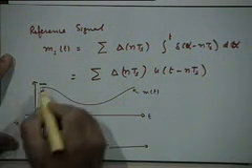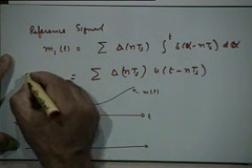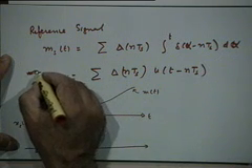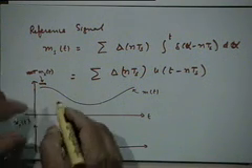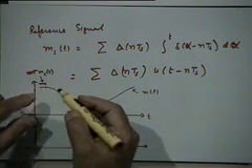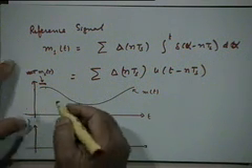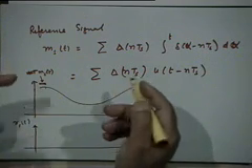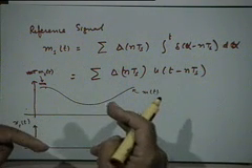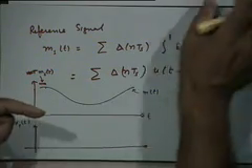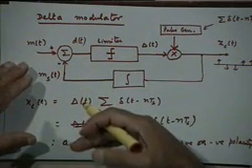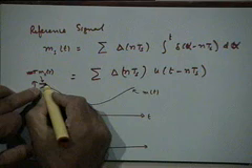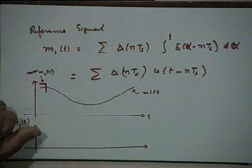Let us say in the beginning you are somewhere here. The reference signal was looking like this. So this was your m_s(t), right? And at this point you are comparing m(t) with m_s(t). So m(t) minus m_s(t) is negative, right? So the quantized value of delta will become -1, and that will produce at the delta modulator output a negative impulse. That negative impulse, when it gets integrated, will produce a negative step. So basically m_s(t) will go through a negative step. Is that clear? Let me repeat it if required.